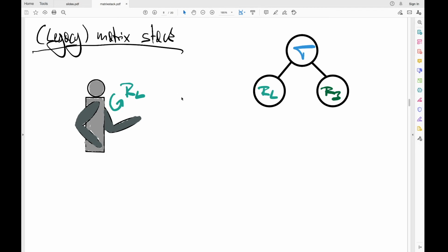This forms a hierarchy. When the robot moves and at the same time the arm moves, the rotation can be thought of hierarchically as a child of the translation. Obviously, when the robot moves, the whole robot moves, and when the arm rotates, it does so with respect to the axis, with the moving axis still being the origin of rotation. So with the translation, the center of rotation for the two rotations moves. This hierarchy is what people would call a scene graph.